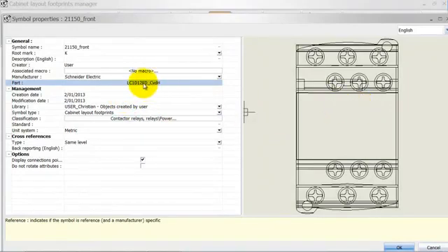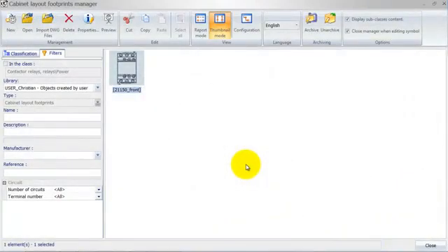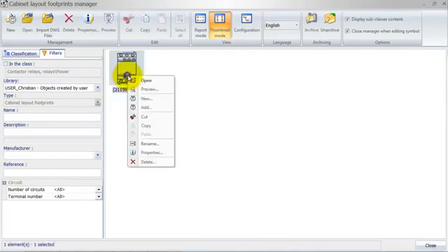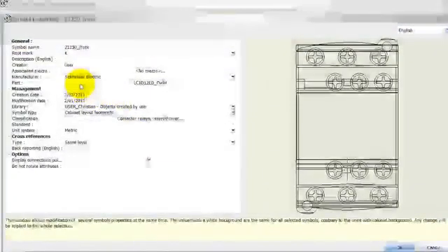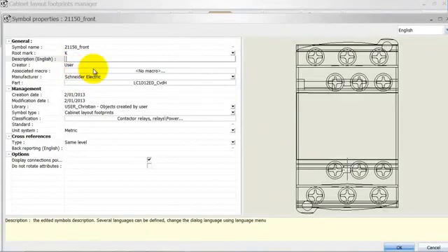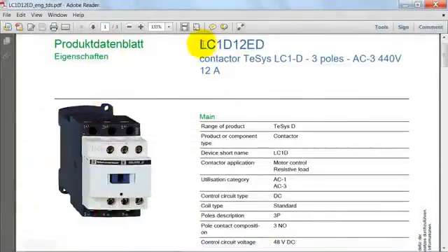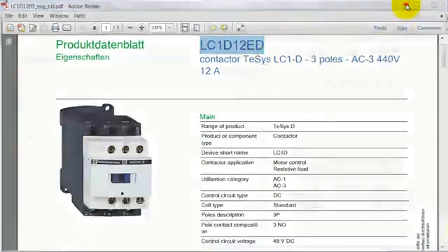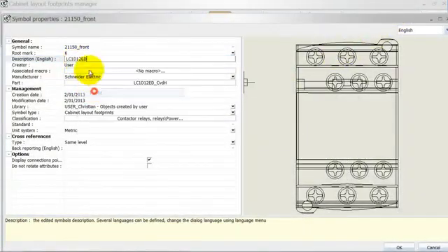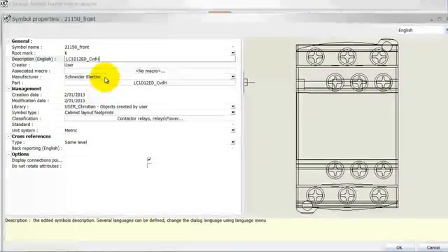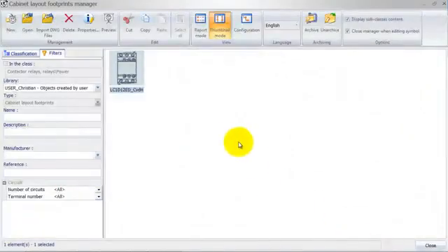Also, of course, if we associate this part to a symbol as well. Okay, so it's going to be cabinet layout footprint. This looks all pretty good, so I can now simply accept that. I forgot to give it a description, I see now, so go back in there and add a description. And what I will do here is simply use the same description as they've done from here and paste that. I always like to add my initials so that I know I customized it. And now you can see it uses the name of the description.